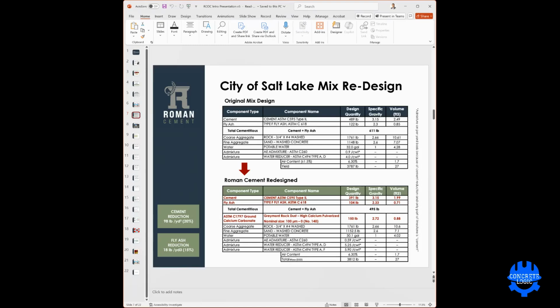And I think there's some efforts to do that, both in ACI 211-7R, which I'm on the committee, and also there's a new standard, ASTM 1697, which is going to permit a blended SCM with pozzolan and limestone, and presumably the limestone in that case would be counted towards the cement, in which case we would not be penalized as we are now for the water cement ratio requirement.